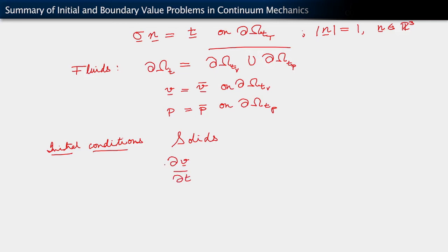But remember, in the context of solids, our primal field is the displacement field, so this becomes the acceleration. Consequently, we have two derivatives, so we have a partial differential equation that's second order in time for the displacements.